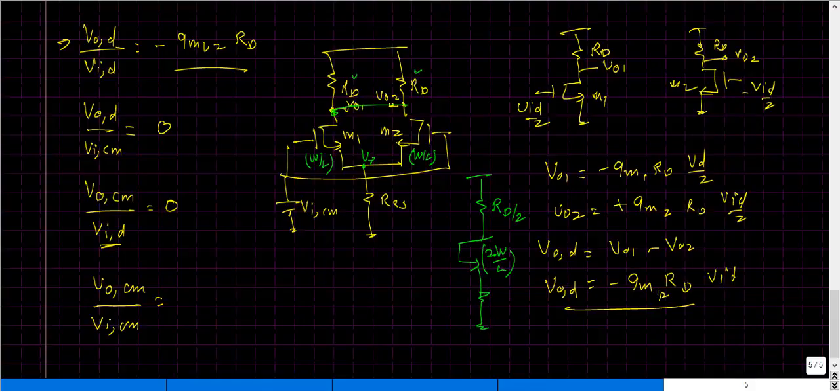And over to the bottom, what I have here is the resistance RSS, and towards the input, which is a common mode input here. So clearly this circuit is the same as our common source amplifier with source degeneration resistance of RSS, and the gain from the input to the output is nothing but minus RD divided by 2, over the source resistance.